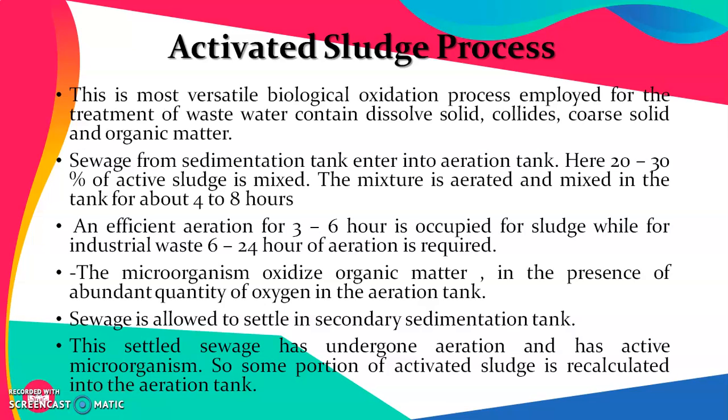So this settled sewage has undergone aeration and has active microorganisms, so some portion of that is recirculated into the aeration tank once again. This results in the addition of active microorganisms which have already undergone aeration and are very fast in degrading the wastewater.